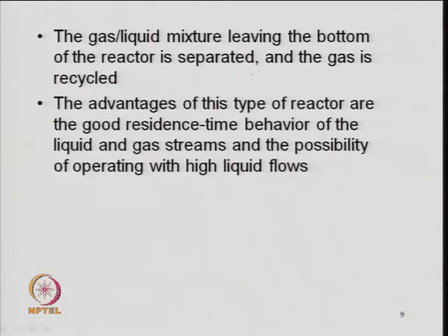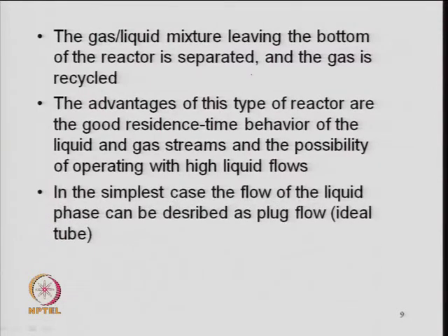So, the advantage of this type of reactor is that they have good residence time behavior of the liquid and gas stream, and the possibility of operating even at high liquid flow rate. So, it can behave like a plug flow also, that is what I was talking about, that you have to maintain the condition, and then see under what condition it resembles that. An RTD study can be done, or flow rate of gas, flow rate of liquid on different shape and size.